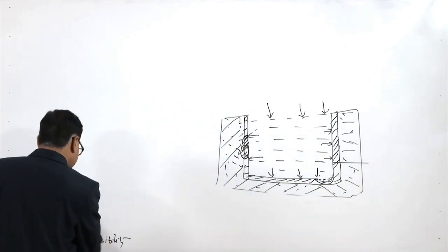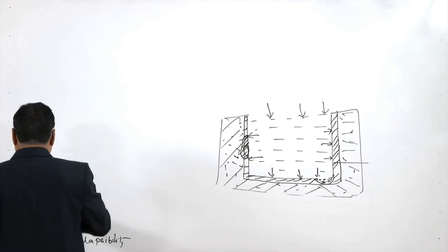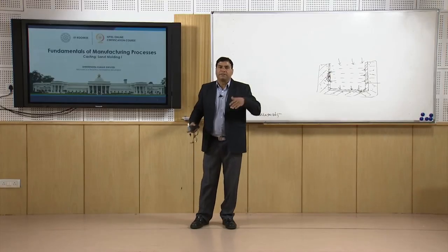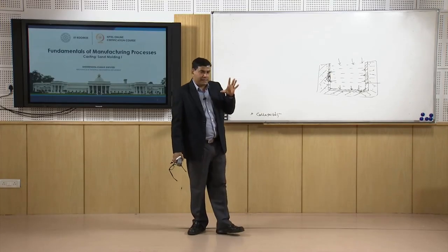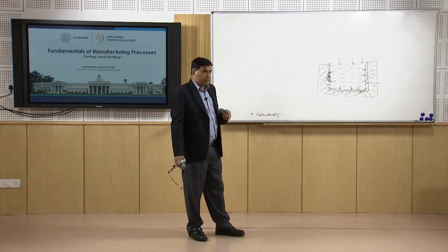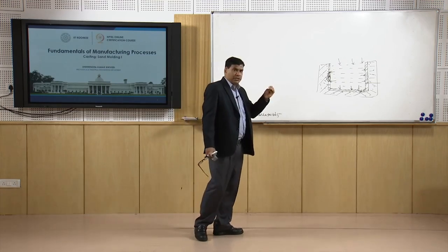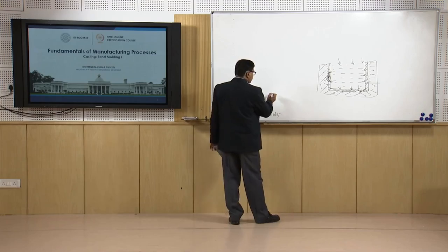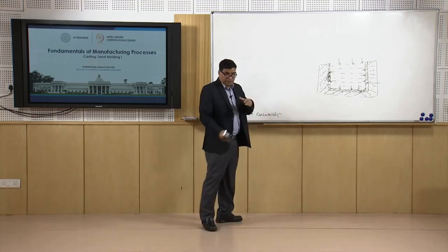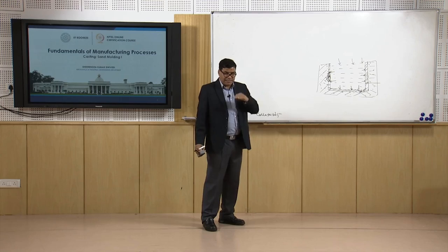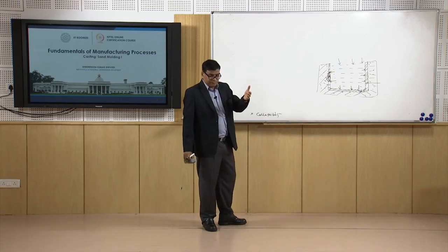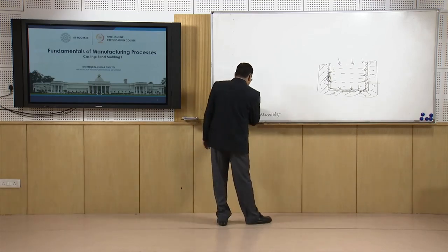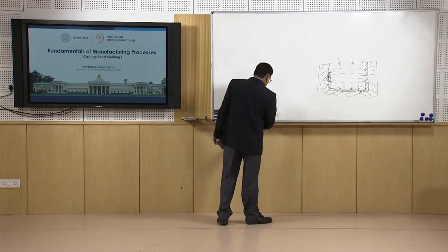So, it is necessary that the mold has the required refractoriness, and it depends upon a number of factors, like the type of clay selected, the size of the sand grains, and the temperature of the molten metal. We need to see that there is proper compatibility in terms of refractoriness between the molten metal being used for the casting as well as the refractoriness of the mold.